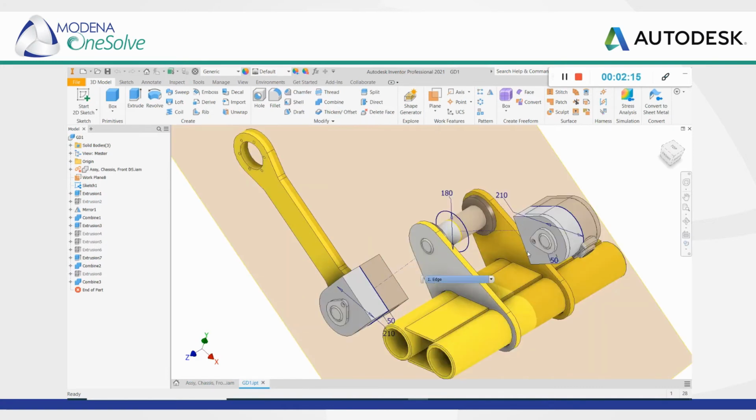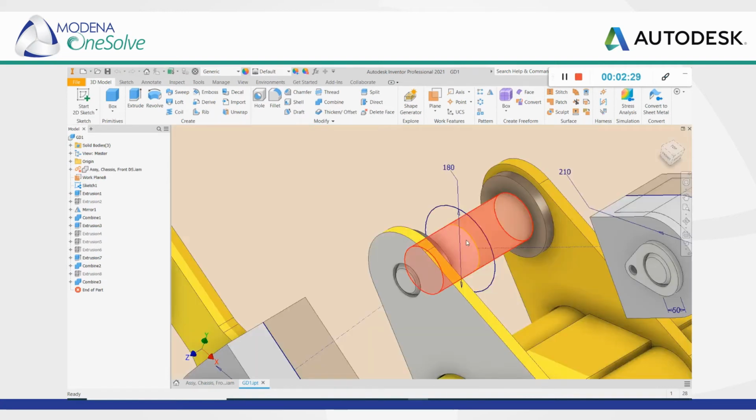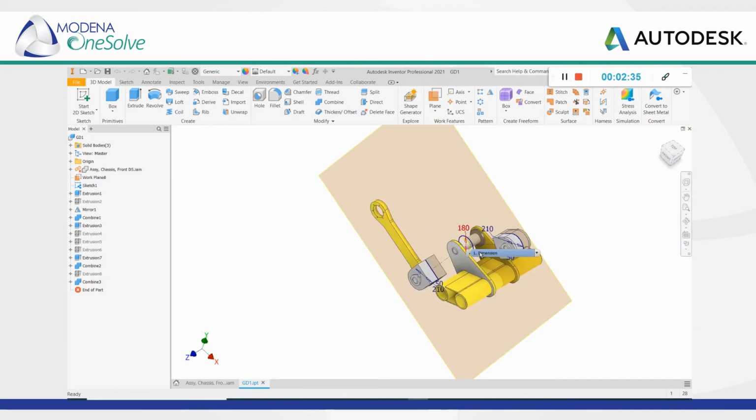So in this component, I have already created obstacle geometry at this top link over here. Okay, those solid bodies will highlight blue, and over here at the bottom. So all we're missing now is the preserved geometry that the arm will fit around at the center of this pivot point. Now at this stage we want to get this information into Fusion 360 so we can start the generative design process.